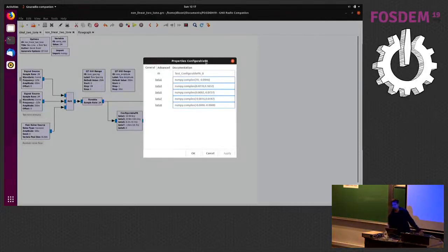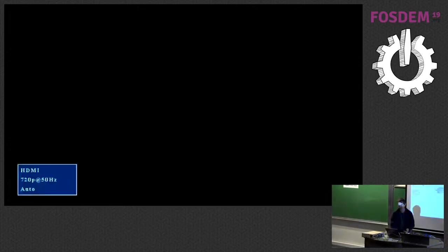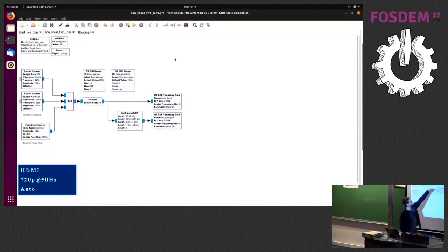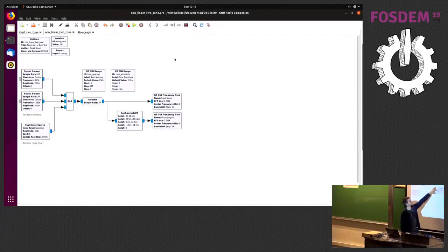No? Well, I'll just describe it then. So on the configurable PA block parameters, we have the alpha coefficients. So those numbers that we were seeing in the equations in the slides, you can enter each of those up to the ninth order. Yeah, okay. They're called beta here because it is actually mapped on the distortion side, but it's exactly the same math. So we have a beta 1 for our fundamental frequency, third order, fifth order, seventh, and ninth order distortion.